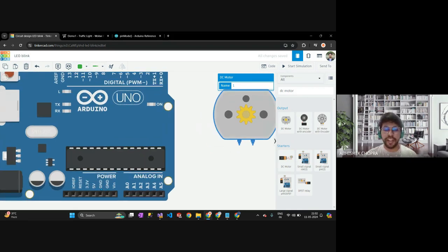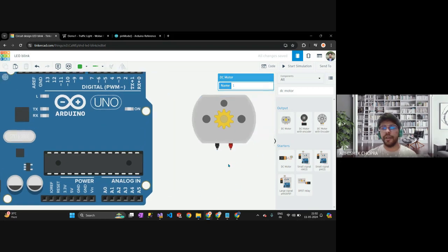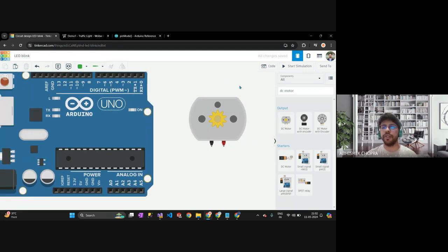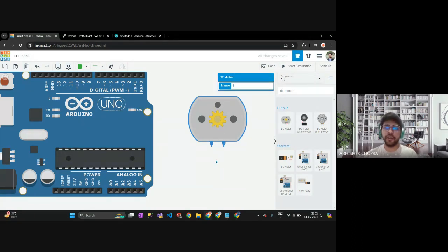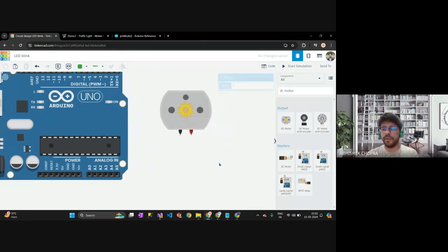So what Arduino can give you is only 5 volt, nothing more than that. But we require more voltage to run this particular motor, right? So in that case, we use different logics. And since we have to define two types of voltage here, we'll attach a different source, right? So I'll just give a battery to it and then attach it somehow. I'll tell you that also. We will be covering that also. So in that case, we want to differentiate between two types of voltage, right? Two types of voltage that we are getting from source.